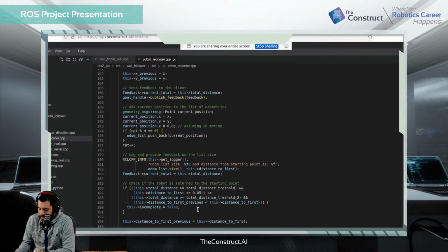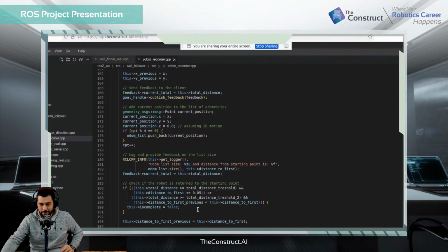And then just one last question to do with actions. What is the advantage of publishing your odometry as an action feedback rather than just printing it out on the terminal? Basically, the question is, what is the advantage of an action feedback? Okay, the advantage is that it will react. If I just print it on the screen, it won't react when I reach my goal.